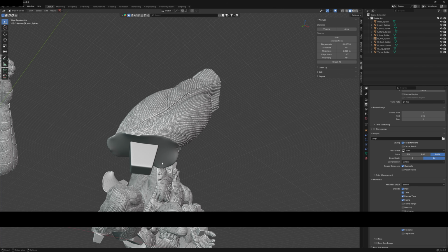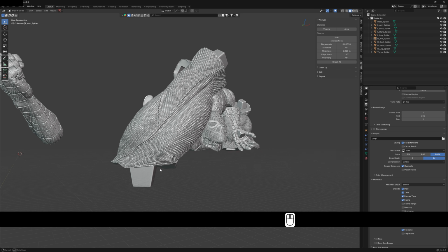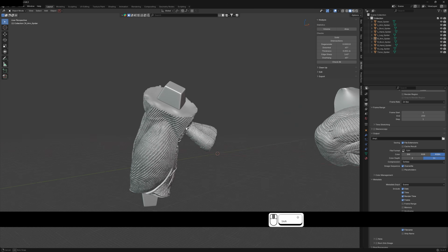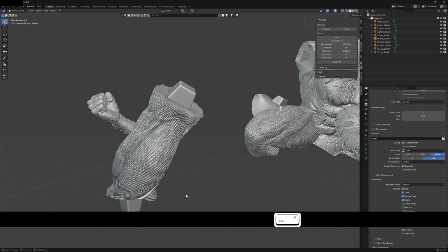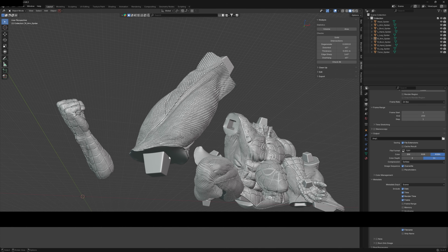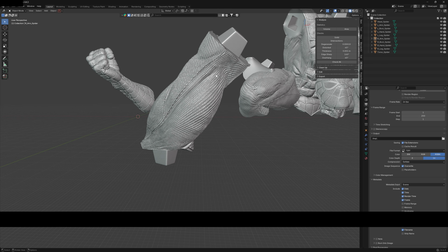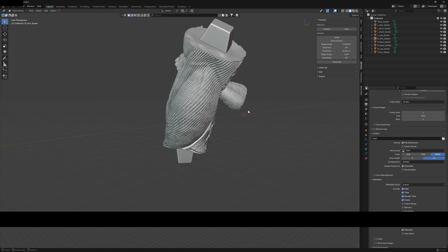You'd have all your supports here, which would make this a bit of a mess, but hopefully these edges would be in good nick. And then if this printed all the way up like that, I think you wouldn't have too much of an issue with that printing. The only issue you would have is making sure the supports are strong enough for the weight of this, to not topple over or get knocked over.